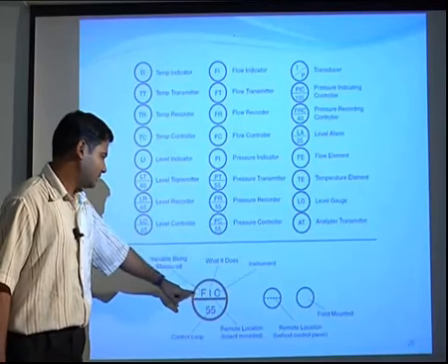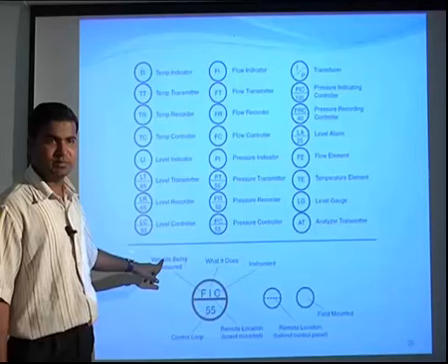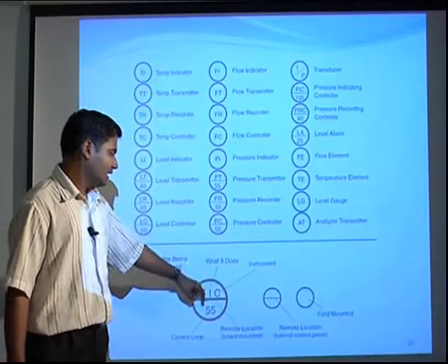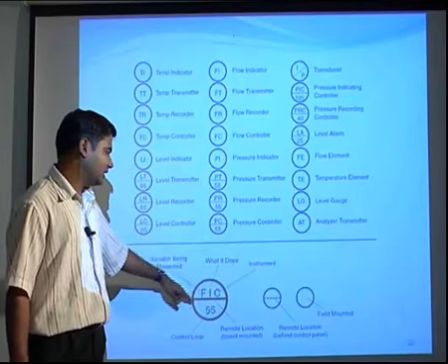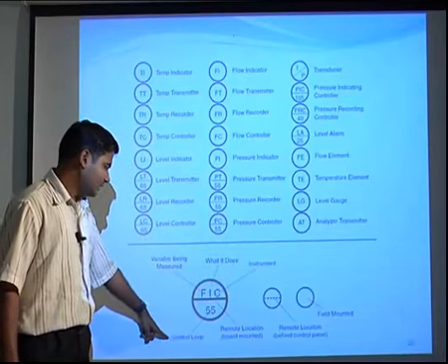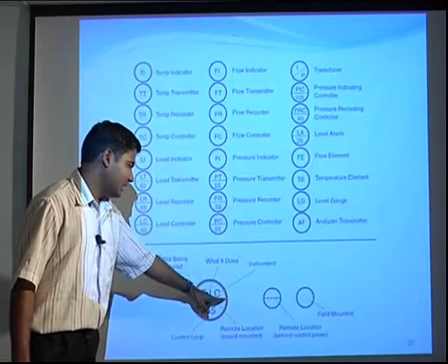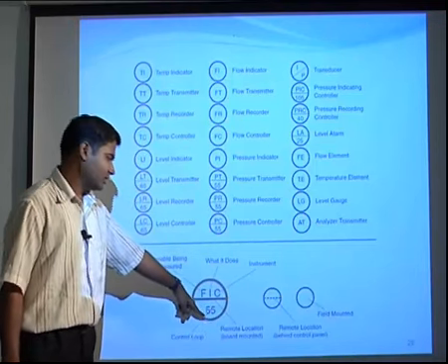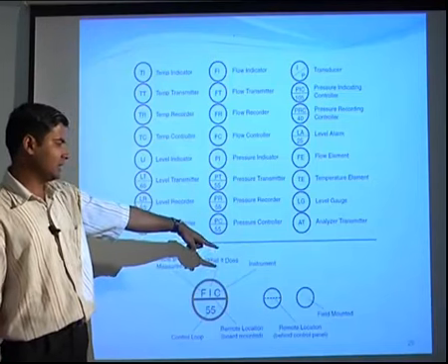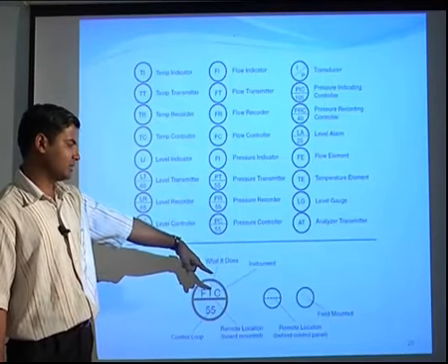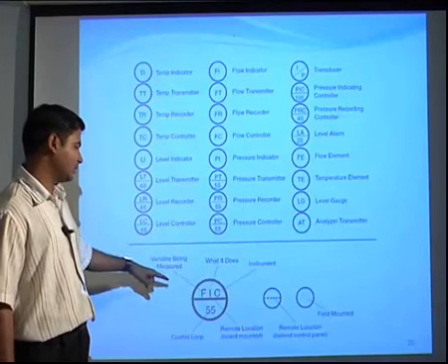First it denotes the variable being measured. The second and third denote what it does, and what instrument is used. The numbers give the control loop, and the line represents remote location or board mounted. Without a line it's field mounted, and with a line it's a remote location, meaning it will appear behind the control panel.